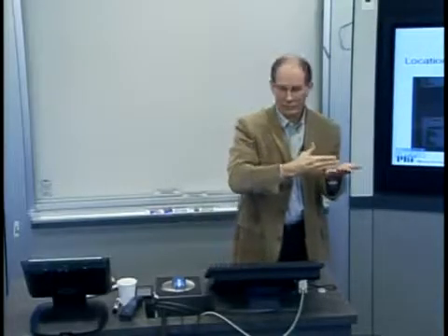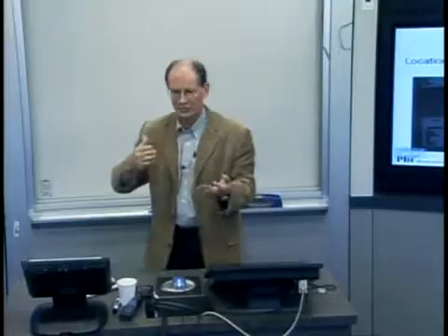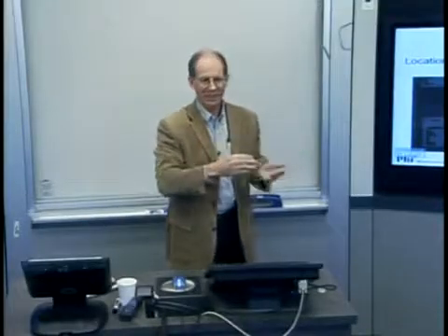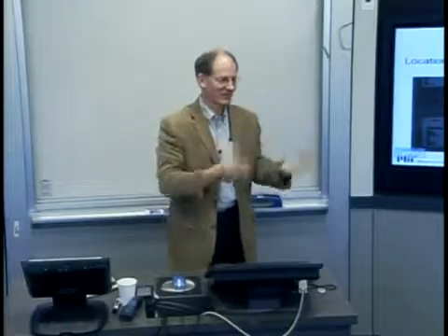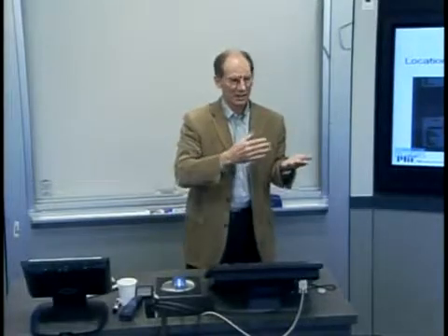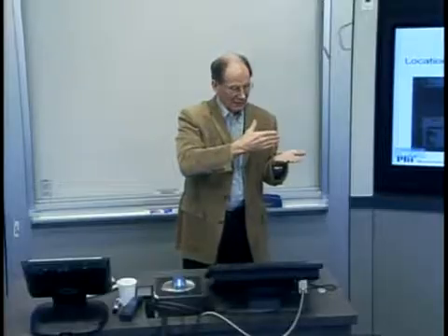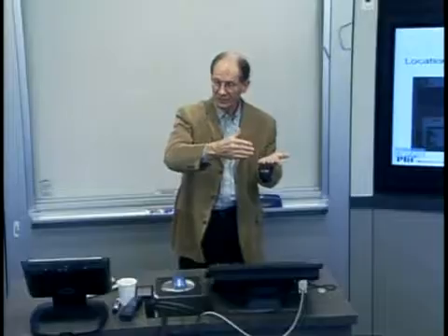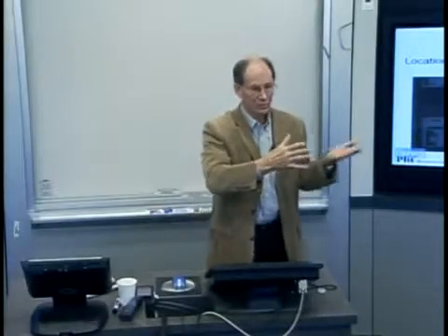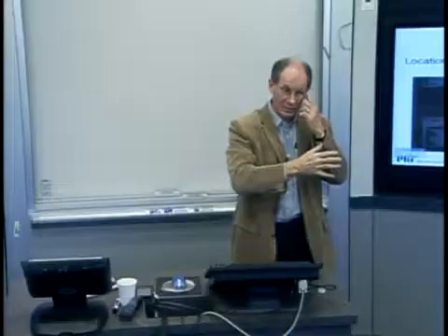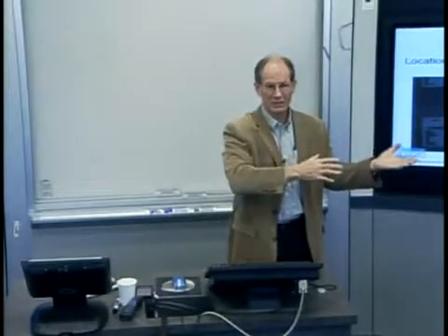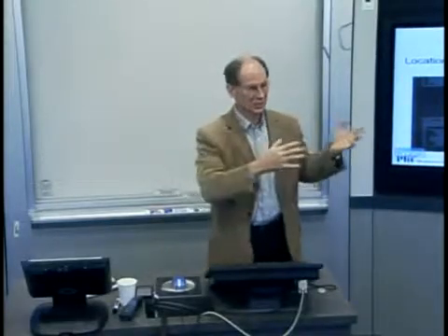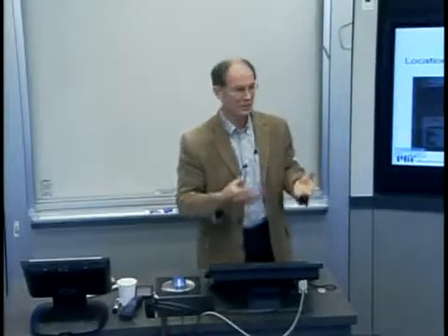Okay? And one of the things you want to think about when we're talking about manufacturing is always question any statement of uniformity or constancy or things like that, because inevitably there will be variations because the topography of the substrate might change. Who knows? And in fact, it does happen, especially as you go to larger and larger wafers. You get important variations in the chamber, temperature variations. You could get concentration variations. All these kinds of things can cause problems.